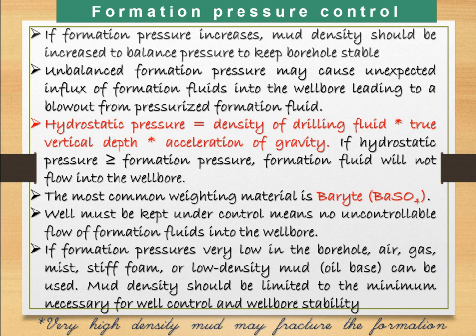Often we might have seen during drilling a lot of fluids coming out. That is the condition where formation fluids are at high pressure. So in such a condition, what is required? We need to enhance the drilling fluid density, because hydrostatic pressure equals the density of the drilling fluid multiplied by true vertical depth multiplied by gravitational acceleration, of course. So if hydrostatic pressure is higher than or equal to the formation pressure, formation fluid will not flow into the wellbore. Simple, because by using proper hydrostatic pressure I can regulate the formation pressure.